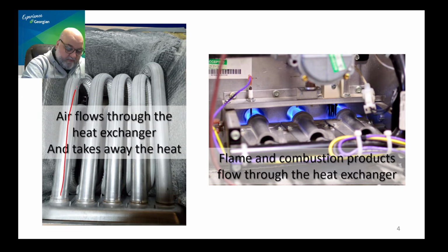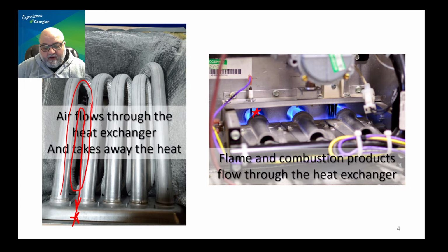This here is the top view of a high efficiency furnace with the heat exchanger and combustion chamber being tubes that go quite some distance, like so. And this point here is the same as this point here. So you are under the impression that the flame is being shot inside those tubes. As a matter of fact, flame is being induced into or sucked into those tubes.